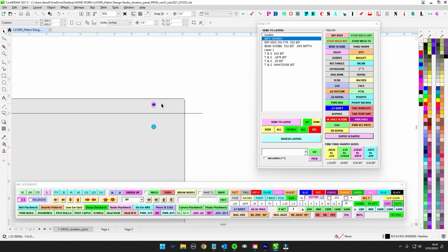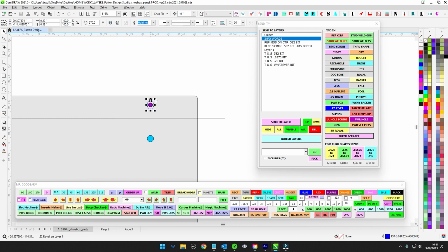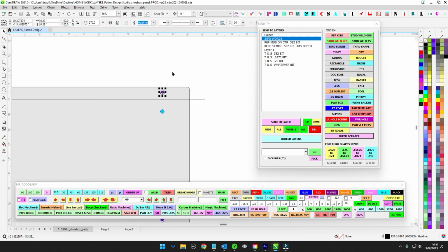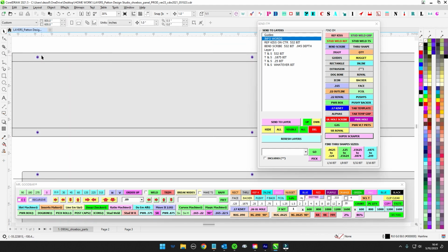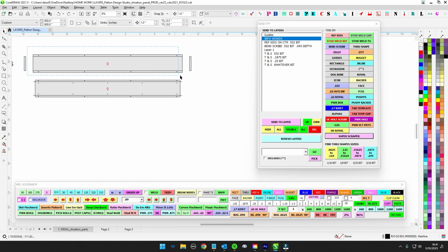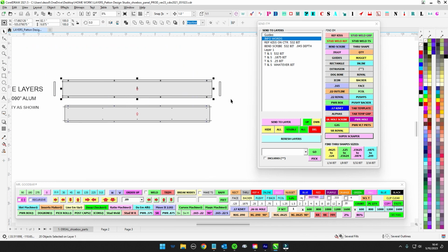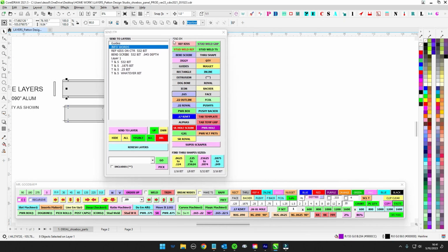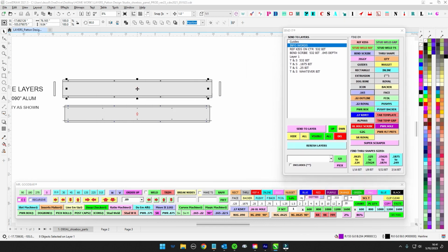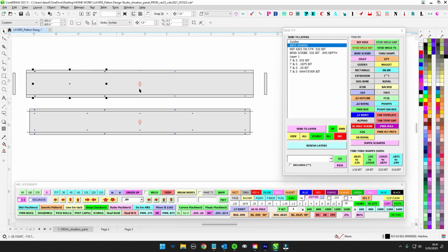If your mounting holes, right, we have the slot, but we also have the other one. We can't send it like this. If we send it like this, this is bad juju. So we know that the clearance is on the face. So if we select everything, just select everything up here. And if you hit 165 right here, it's going to automatically select the 165s because they are named, and you can just hit delete.